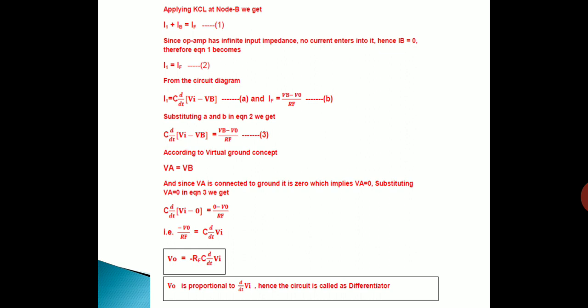What does the virtual ground concept say? The potential at the two input terminals of the op amp should be 0, or there should exist a virtual short between the two input terminals of the op amp. Hence, according to the virtual ground concept, VA should be equal to VB. Now if you see this circuit, VA, the non-inverting input terminal, is connected to ground. So obviously the value of VA is 0.